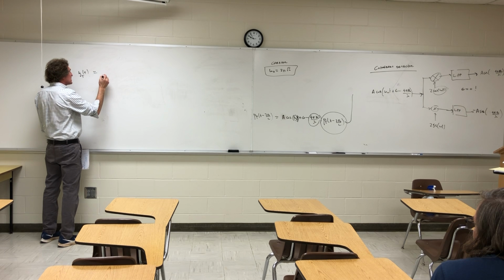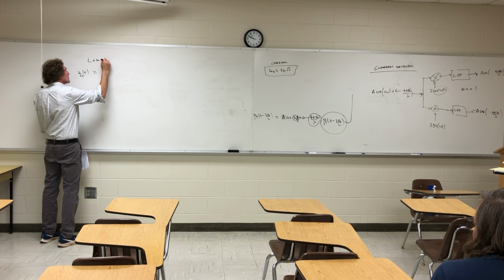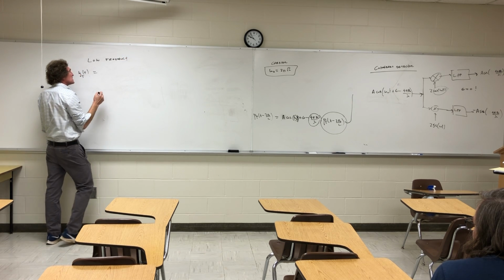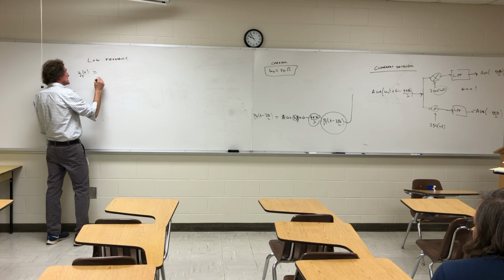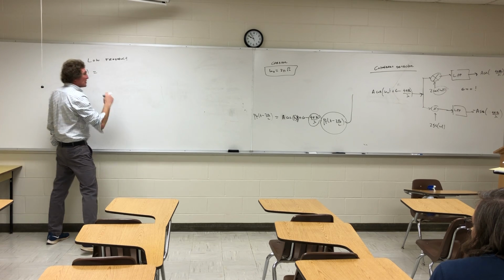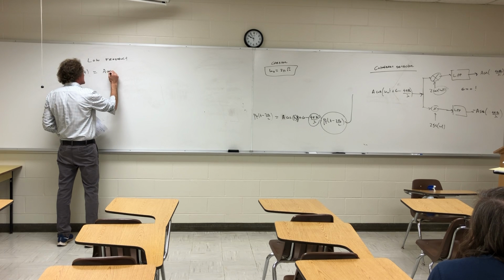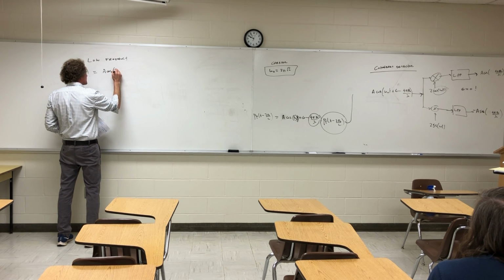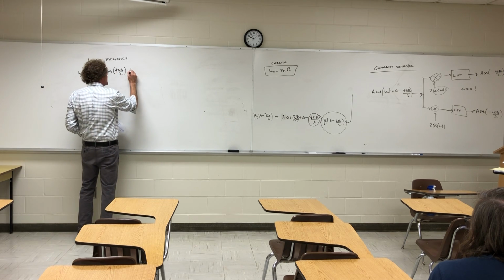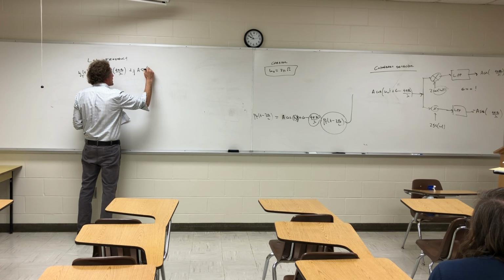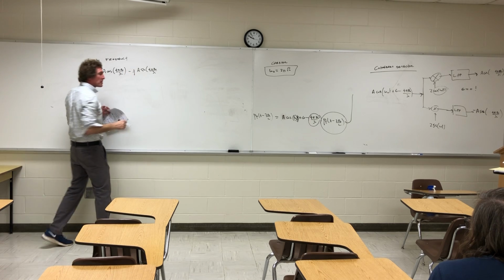The low pass signal is going to be equal to the first signal, which is A cosine of 4 pi r naught over lambda plus j A sine of 4 pi r naught over lambda, but I have to put a minus j there.